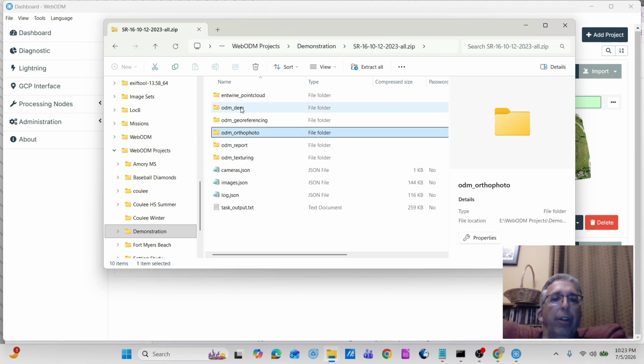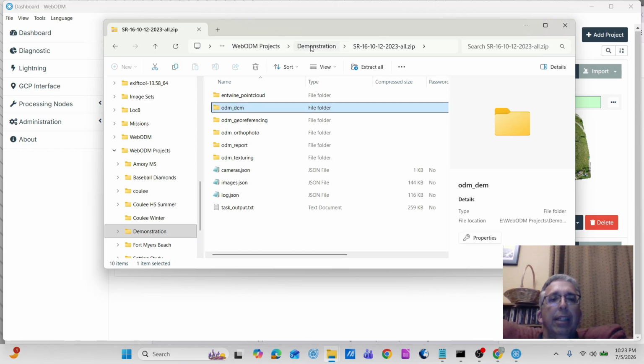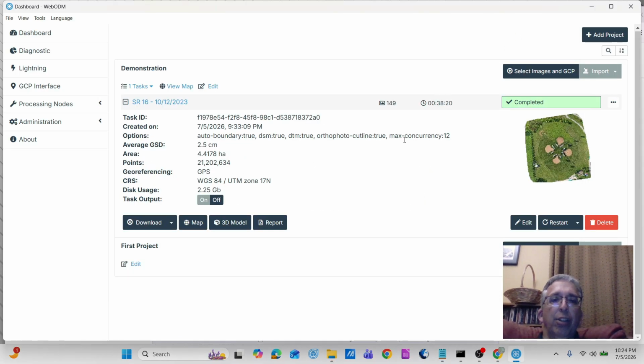And all the other deliverables are also here. File sizes are quite large. At some point, you will run into limitations just based on being able to open your created image in the amount of available memory. So there's always a limitation on how big of a problem you can tackle at a time. So that concludes the overall process of getting deliverables out of Open WebODM.